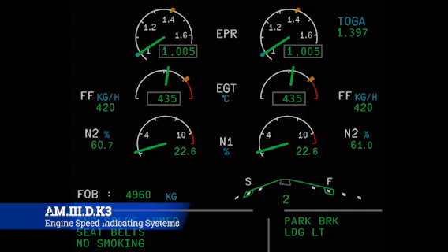More importantly, this is also being logged in the DFDR, or Airbus's version of it, so if there is some sort of problem, you can turn around and download all that information, look at it on a maintenance laptop, and say, oh, hey, look, whenever you get to this point during the flight profile, these things are starting to happen, or we're starting to have these faults, or whatever the thing is. It helps you as the maintainer be very efficient in your troubleshooting, so you can take care of problems before they develop into bigger problems.